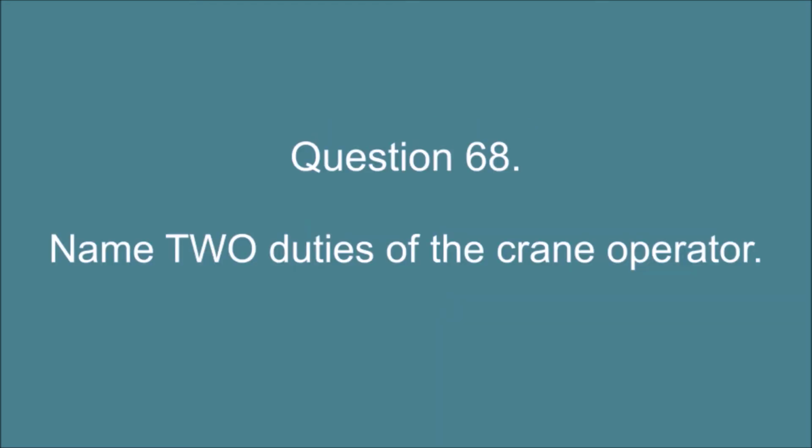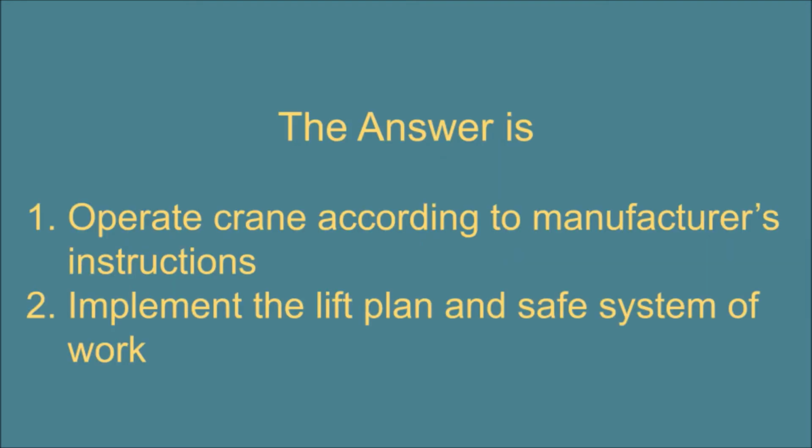Question 68. Name 2 duties of the crane operator. The answer is: 1. Operate the crane according to the manufacturer's instructions. 2. Implement the lift plan and safe system of work.